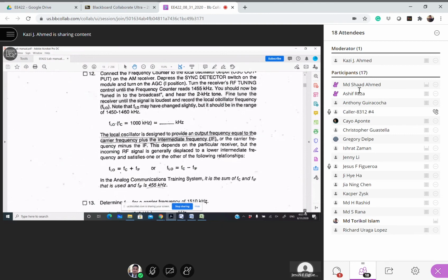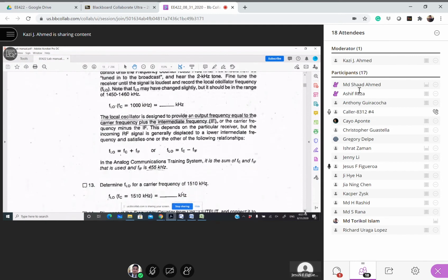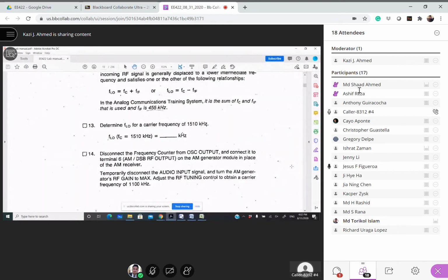Professor, I have a question. Yes. This is Jesus Figueroa. So if the carrier were, say, I don't know, 1200 kilohertz instead of 1000 kilohertz, you would need F local to be 1655, right? Your carrier is 1200, right? Yes, exactly. What it means is, if you send a carrier with 1200 kilohertz, now you have to tune your local oscillator to 1655 to get that signal, right?